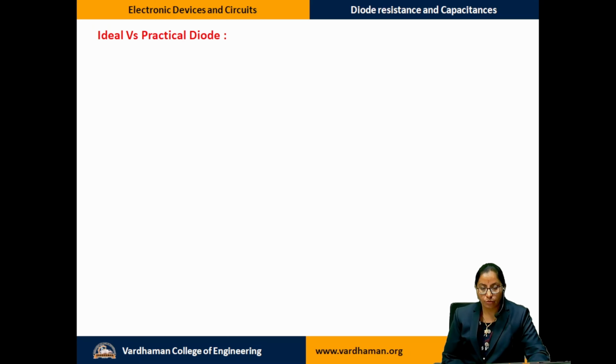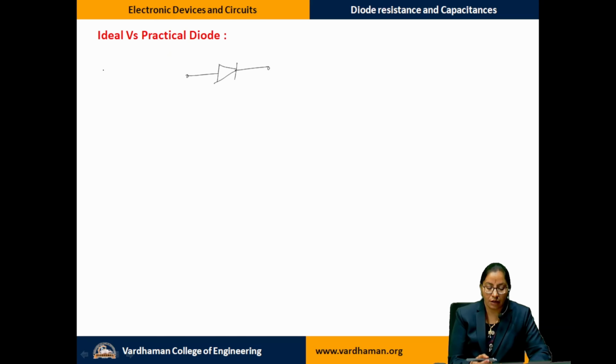So next we shall see what the actual practical condition of a p-n junction diode is, and what the ideal condition is that we take when we use a diode in any practical application. We assume an ideal condition, and we are going to discuss now what we assume ideally versus what is practical. A practical diode, as we know, depending on the bias that we apply, offers a certain value of resistance, and it has current conduction happening. Based on that we also define the equivalent model of it under ideal and practical conditions, draw the equivalent model and define its resistances and capacitances.